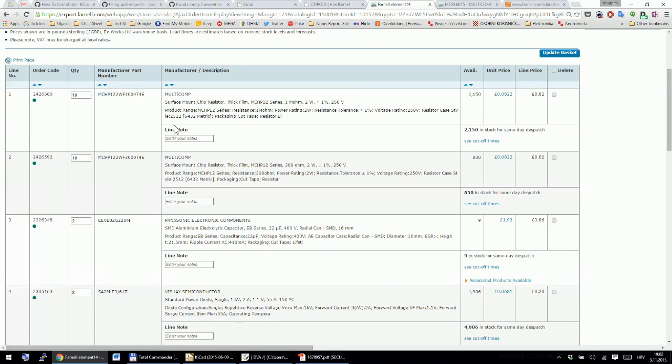I've chosen big beefy resistors because it will be much easier for soldering. If you're a beginner and following this tutorial, or just doing something similar, this will be much easier than soldering very small components. So I've chosen this 2512 size of package for resistors.